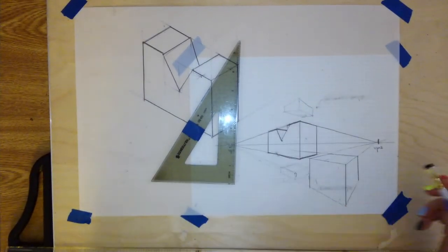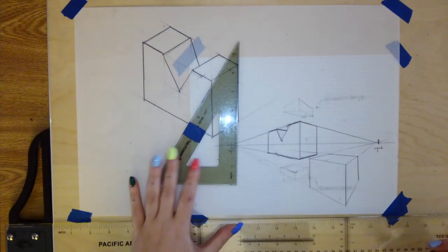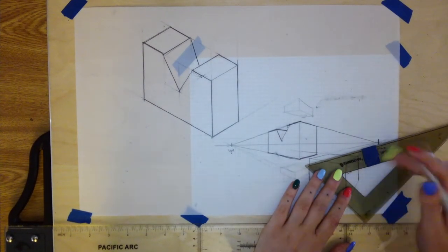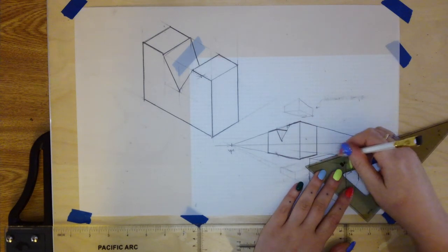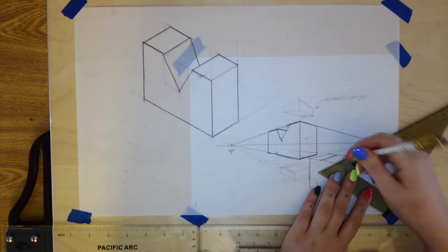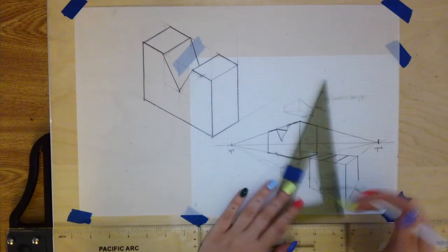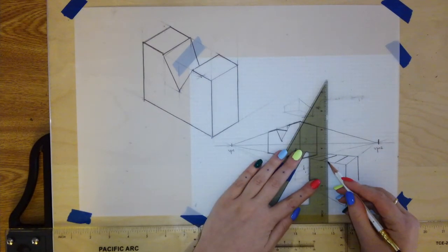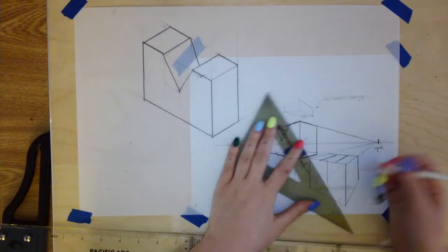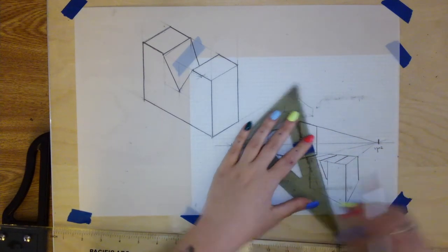And so I've got an overall bounding box now for my object, just like with the isometric, just like with the obliques, just like even with the orthographic. I'm always just starting with an overall bounding box. And then I can decide what I want my depth to be, or what any other little detail features that I might have. So it's always, for me, the easiest way, starting with an overall box and then just kind of carving your way out.